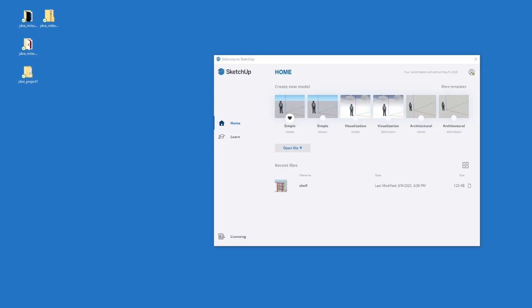The size unit is what helps determine what numbers it accepts if you just enter a number without a unit. It also helps with scale. So if you're working on a much larger project, then you might want to use something more like meters or feet, if they still have a feet template, because you end up running into issues with zoom if you use something like feet or meters when trying to zoom really small. So let's go ahead and stick with inches, and we can just click on this right here and get started.